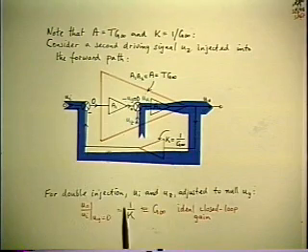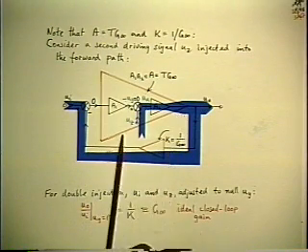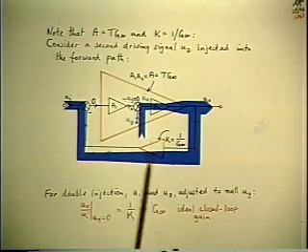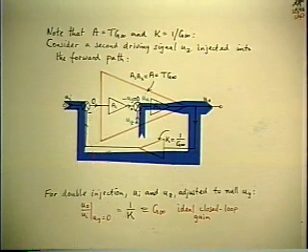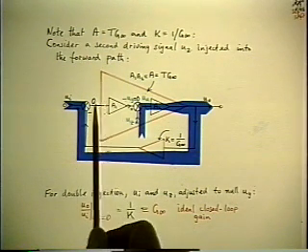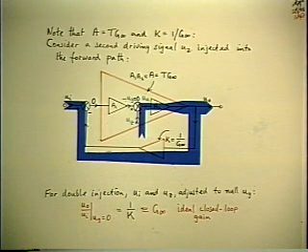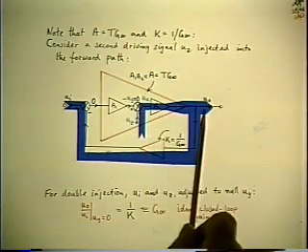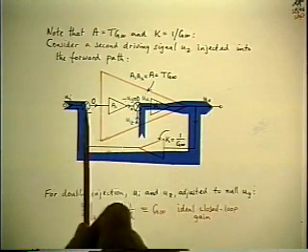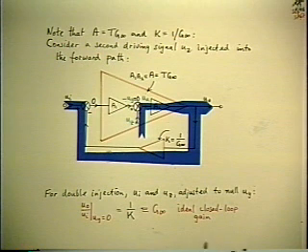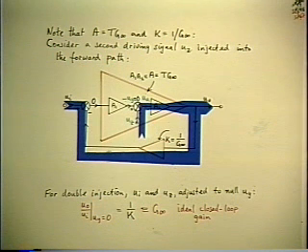And the way you set it up is you fudged it by using the second input to drive the output to the proper level that takes over the position of the amplified error signal. So you don't need the error signal anymore. That's actually what you're doing when you set up the null condition. You're adjusting the second input in such a way that it drives the output to take over the role of the amplified error signal. So this is another application for null double injection, besides the extra element theorem.